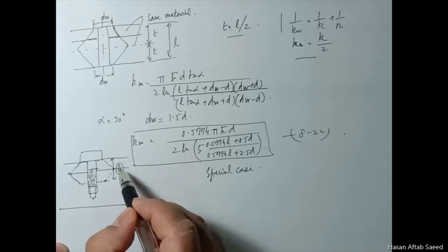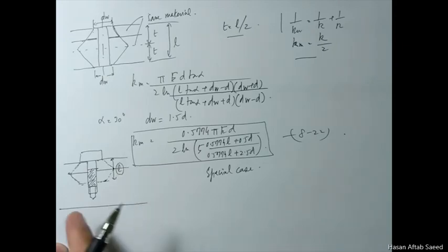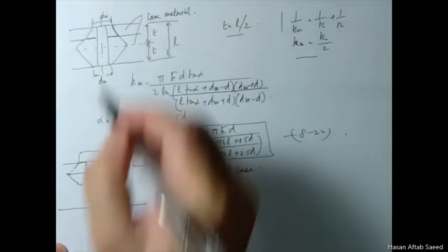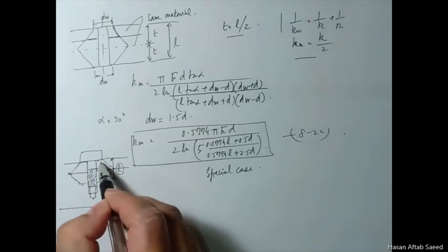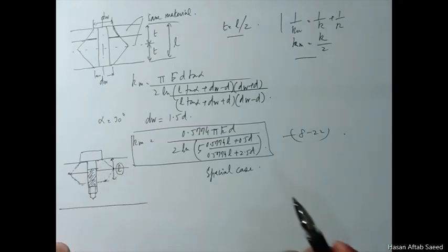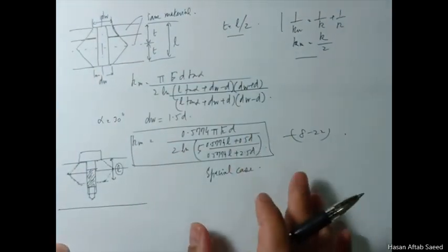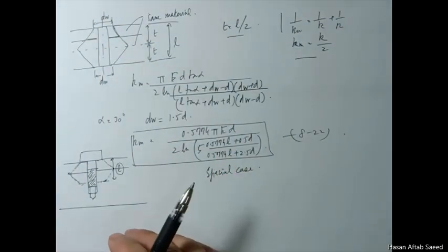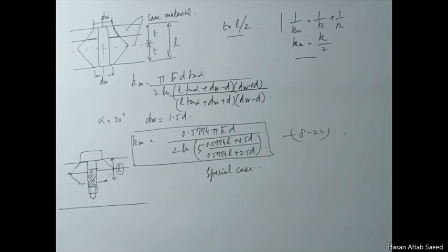And this L is the same, although there is no nut here, the distribution spans around this length L. So all these expressions that you have calculated are for nut and bolt arrangements as well as cap screws and studs or whatever you are using.